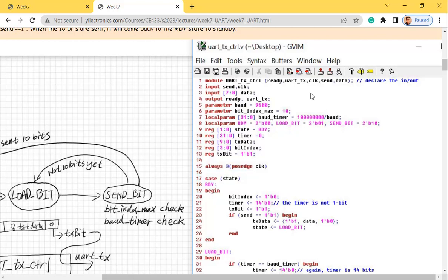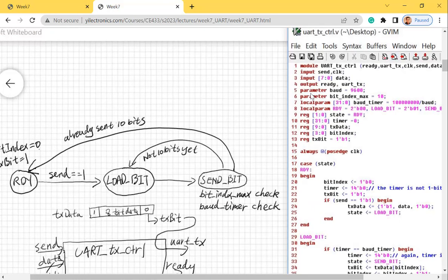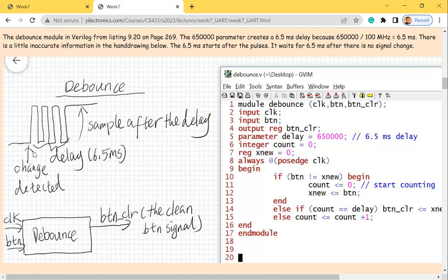You press it one time, you think it's just a very clean logic 1, but actually it's vibrating. It's a mechanical contact, so the mechanical material will vibrate. If you have a high-speed camera and you record it, it's going to be like this instead of a clean contact. It's a mechanical switch, so you press it, it's going to swing back on and off several times until it's giving a clean 1. In that case, the digital system is really fast and smart, so it's going to detect all the swings.